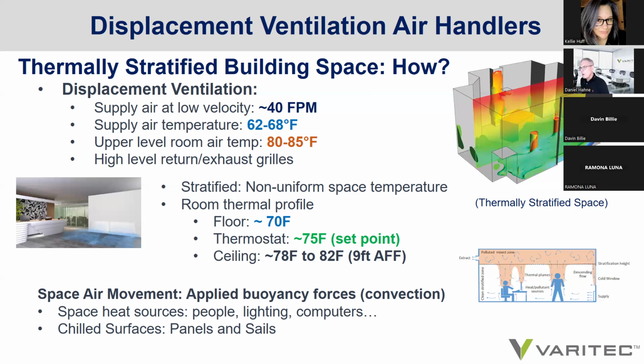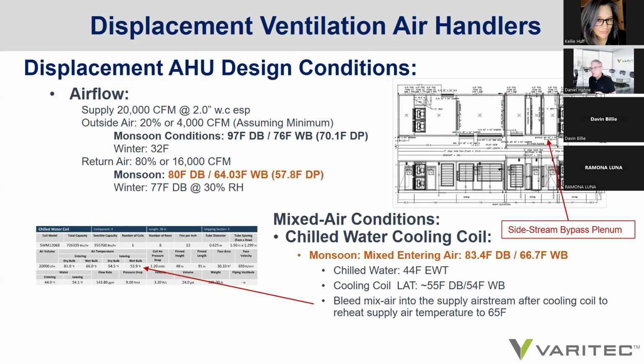It worked very well. The reason why you might want to look for this solution is, for one thing, they're low static pressure systems. Second thing is you can reduce your fan energy. And thirdly, you can, in Phoenix, Arizona, double your economizer hours by providing 65 degree air versus 55 degree air. So those are some of the motives for it.